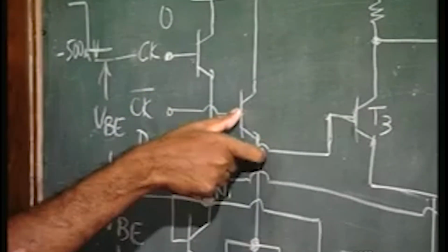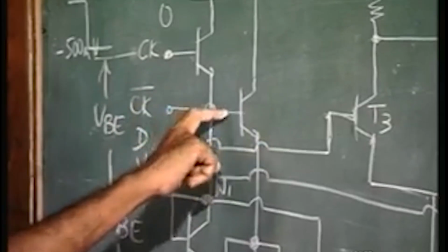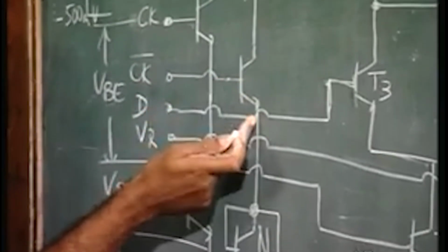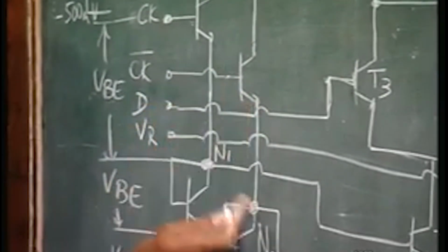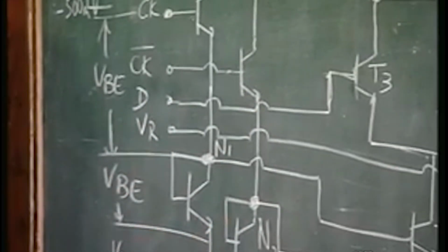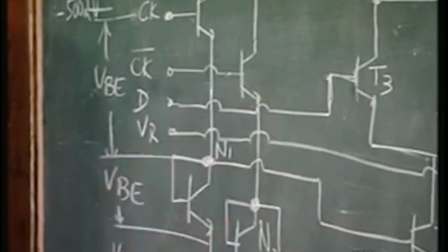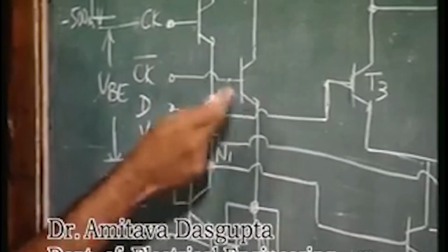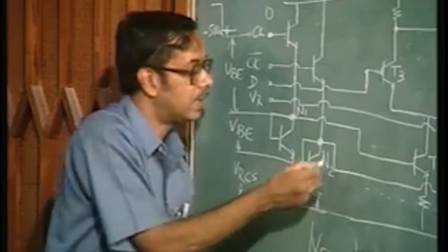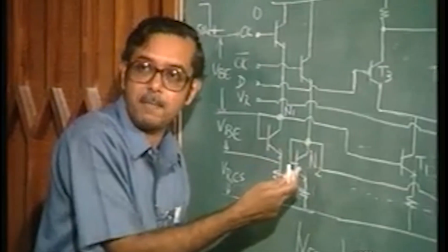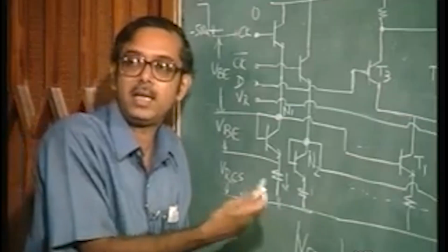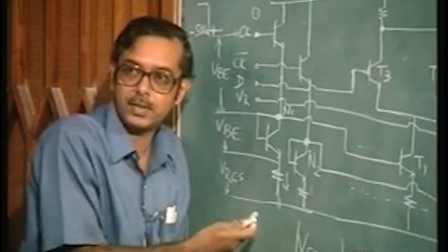Basically, 1.5 volts is going to be dropped between this VBE of this level shifting transistor plus this diode arrangement here. So, the maximum voltage which can be dropped if both of them are carrying the same current per junction is 0.75 volts. So, this transistor is going to be off, which is less than the requirement of VBE, which we have said is 0.9 volts.